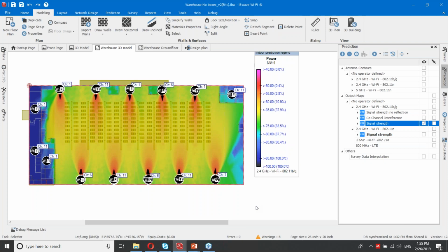Okay. This question is, if the boxes are empty in the demo, how can extra attenuation be taken into account due to the merchandise located inside the boxes, or what's the best approach to handle that? Well, I have filled out the boxes. They're wooden boxes, and inside I assumed that they're not empty. I assumed paper inside. I assumed that this is a warehouse full of books. So that's how I accounted for the merchandise. The merchandise in this example was books.